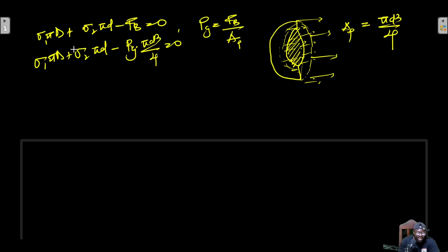If the surface tensions for the two interfaces are different, and the larger diameter and the small diameter are not the same, then you can apply this equation. But mostly for soap bubbles, the larger diameter is almost the same as the small diameter, or at least we can make that particular assumption.